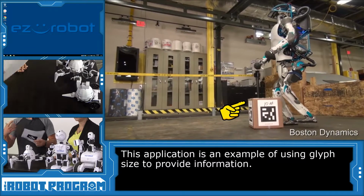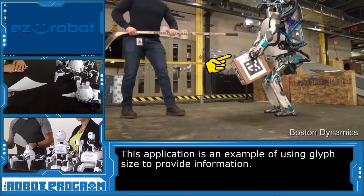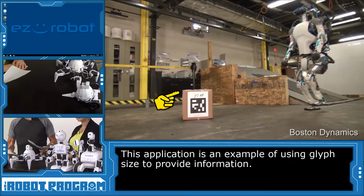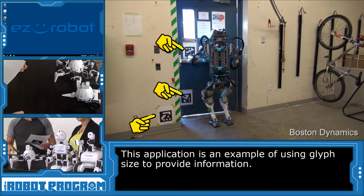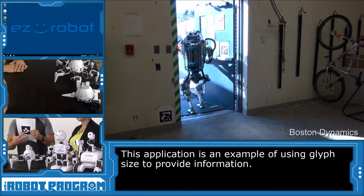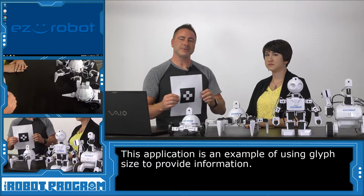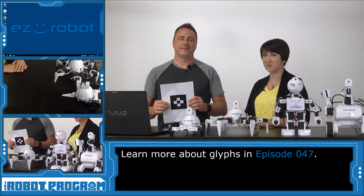Yes. Now, this is an application you will see if you watch videos about the Boston Dynamics robots, for example. You'll see glyphs posted around various areas in the room or on boxes. Glyphs are used for robots to be able to identify how to pick up a box or how far away the box is, based upon the size of the glyph in the camera image. So we're going to be using the size of the glyph to identify how close it is to the robot's camera. And if you want to learn more about glyphs, you can check out one of our other episodes.